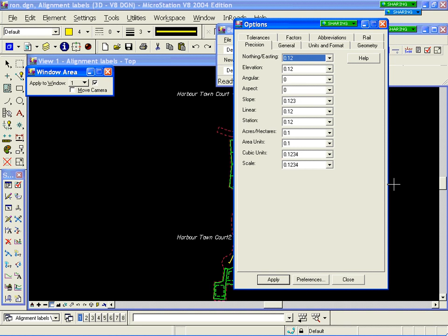This is where for all the products you will set such things as precision. And if you notice down in the cubic units, I have bumped the unit up very large. We're looking at a very small residential area, so my flows are going to be pretty small, so I need 3 to 4 decimal places to see what our flows are going to be in with this.